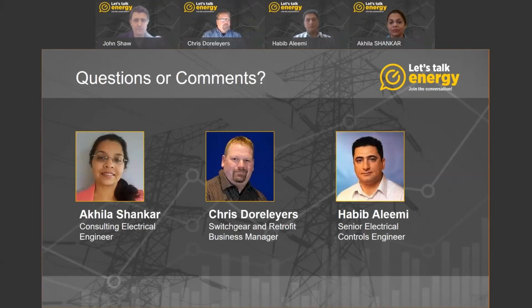Can diesels be paralleled with natural gas generators? Sure, Chris. The answer is yes. We have examples of these projects in Ontario where we parallel diesel generators with natural gas generators. However, the diesel generators have a better transient response compared to natural gas gensets.